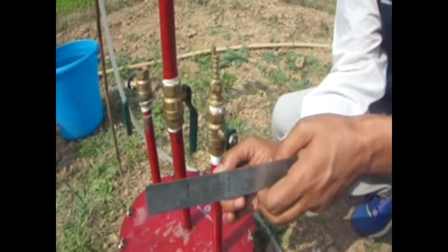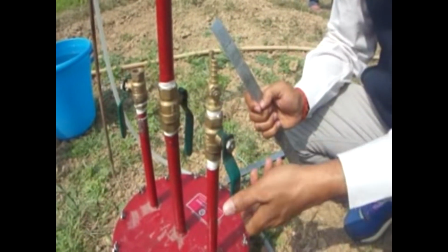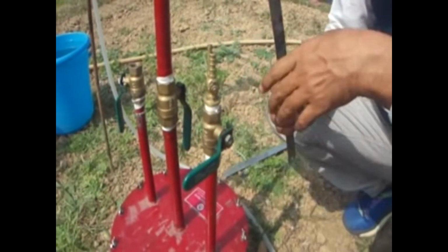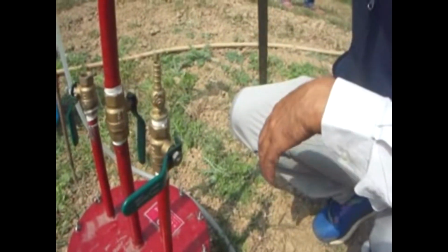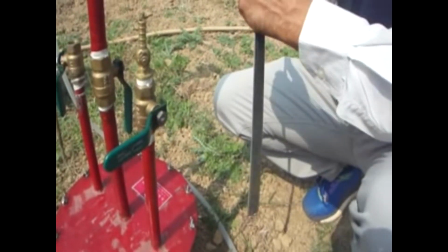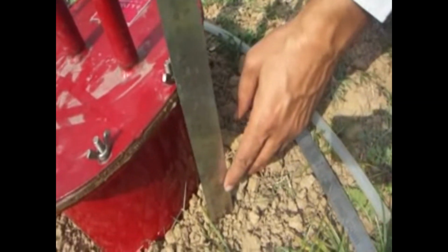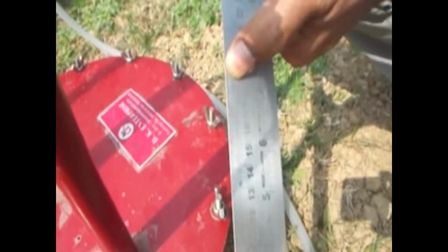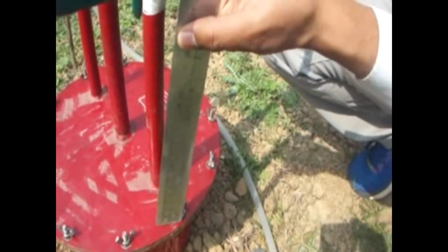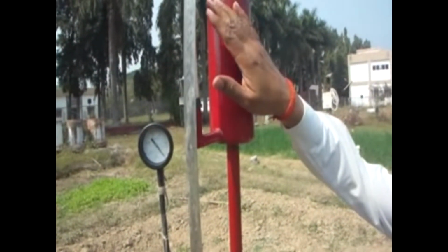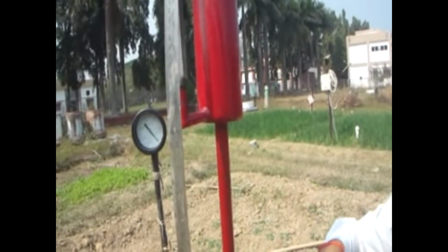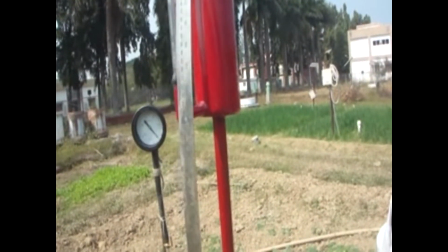So now you can parallelly, once it's parallel it is open and it is closed. So let us close this. Supply valve is open and this is also open. We need to also measure the different heights, or we can say head. So from surface, let us take this height of this cylinder top surface. So how much it is? It is here 18 centimeter, and from 18 we will measure what is the height of this head in the supply when it is reaching constant condition.